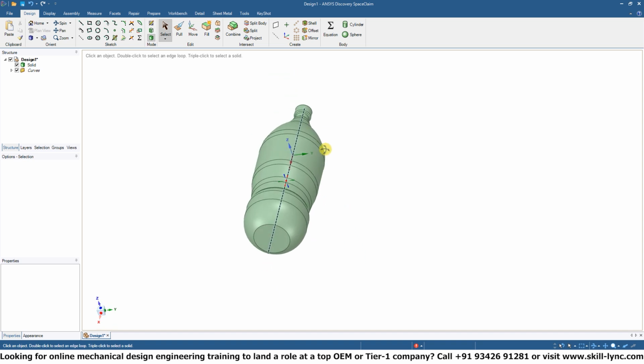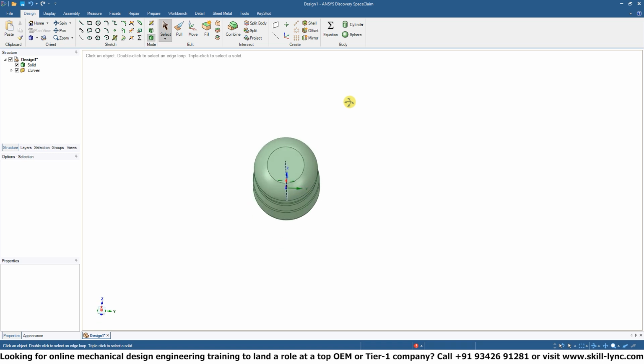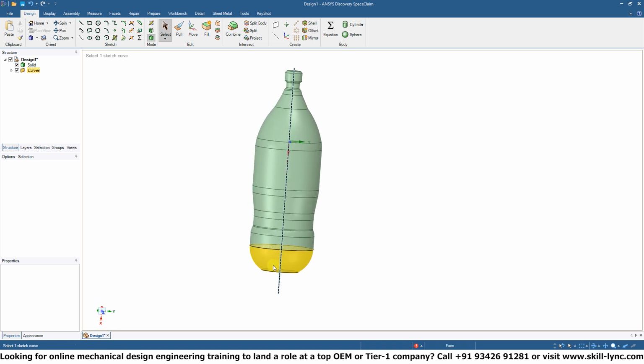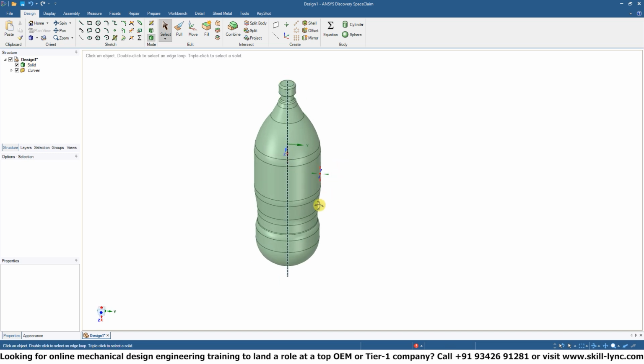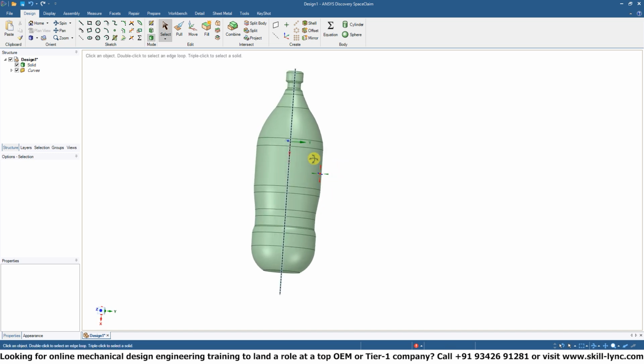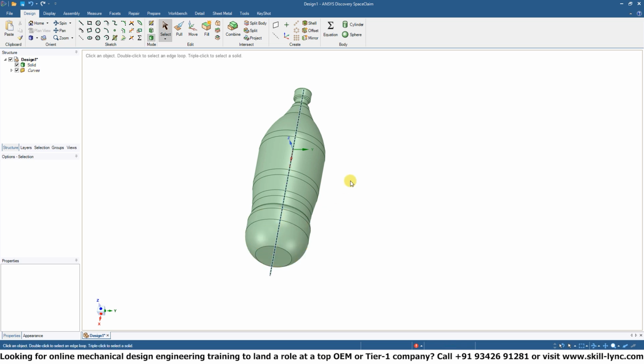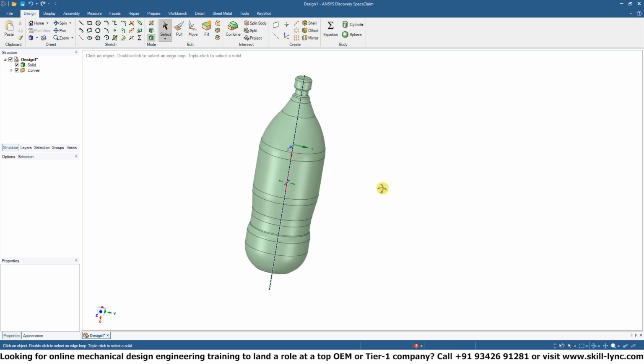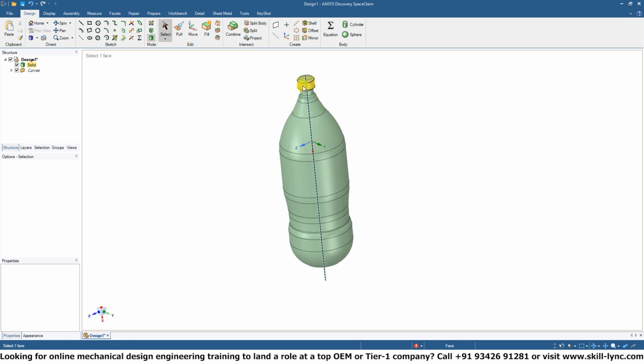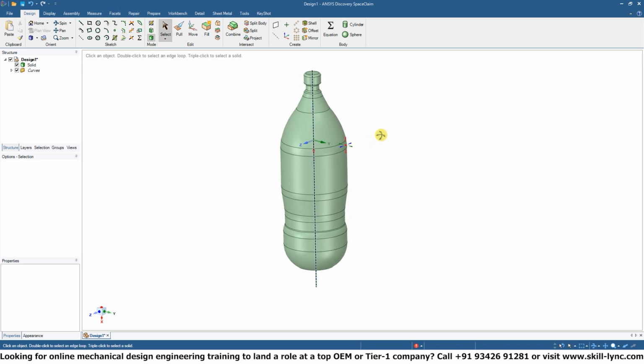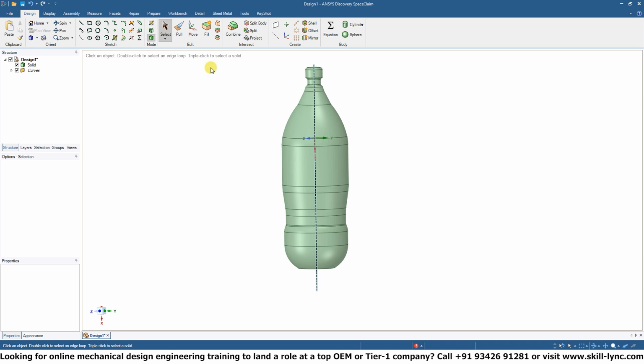Obviously, you can add a few more features on this 3D geometry if you wished, because the bottom end does not match the bottle 100%. You can do a few cuts on there, which we'll cover in week 2. But you can see just after 1 week with some simple line and bend tools and some reference geometry, we can create some real life applications, real world models off of reference geometry and reference sketches.